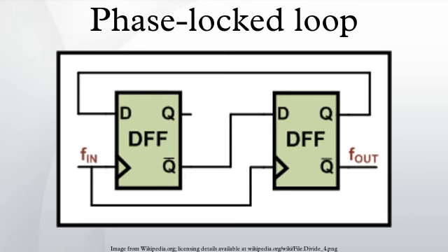For instance, the frequency mixer produces harmonics that add complexity in applications where spectral purity of the VCO signal is important. The resulting unwanted sidebands, also called reference spurs, can dominate the filter requirements and reduce the capture range and lock time well below the requirements. In these applications, the more complex digital phase detectors are used which do not have as severe a reference spur component on their output. Also, when in lock, the steady-state phase difference at the inputs using this type of phase detector is near 90 degrees. The actual difference is determined by the DC loop gain.